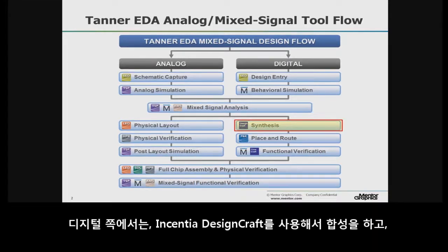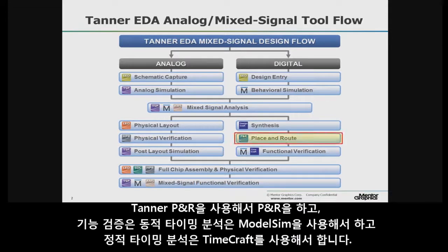On the digital side, we do our synthesis in Incentia's DesignCraft. We use LEdit for the place and route using HyperPNR, and then functional verification using ModelSim for dynamic timing analysis and Timecraft for static timing analysis.